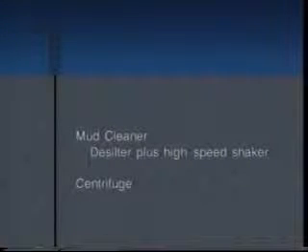A centrifuge is sometimes used in weighted mud systems to remove very fine particles. The mud enters a rotating chamber, and the centrifugal force separates the mud stream into 2 components, liquid phase and solid particle paste. Chemical additives are sometimes used to flocculate the mud, causing aggregation of particles and facilitating their removal from the liquid. This approach is not recommended, however, due to the adverse effects of the additives on other mud properties.